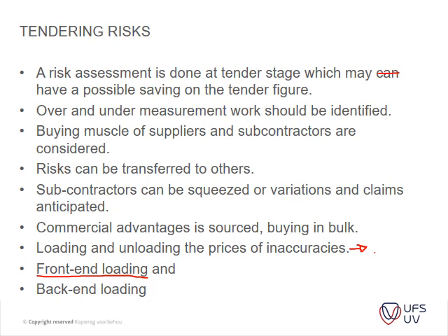When you remeasure your work on site, your excavations might be much less than you anticipated, in which case you will lose on your contract, because your back-end items will not have the necessary rates or bulk of finance to carry you through the project. So please note that this is a very risky item, and the QSs usually pick it up when you do the leveling of your rates before you get appointed.